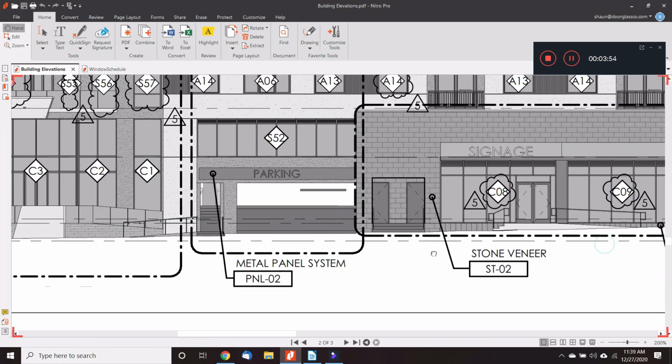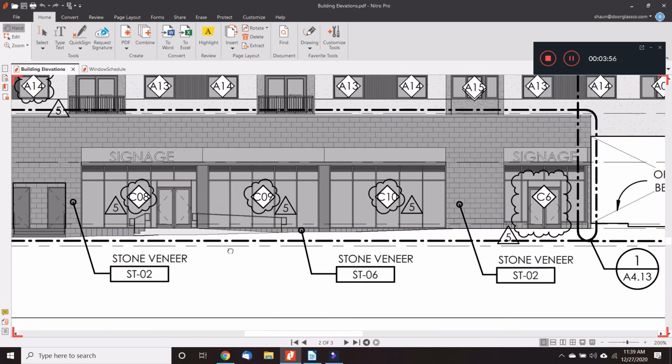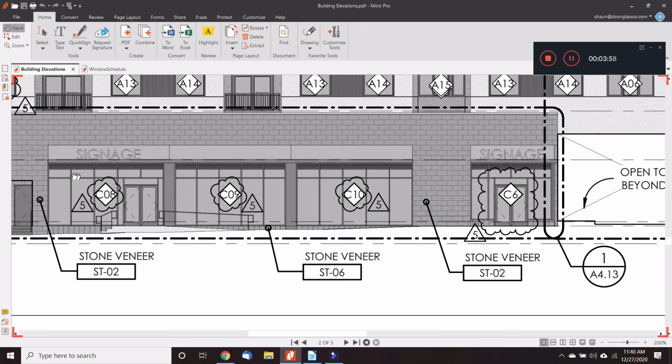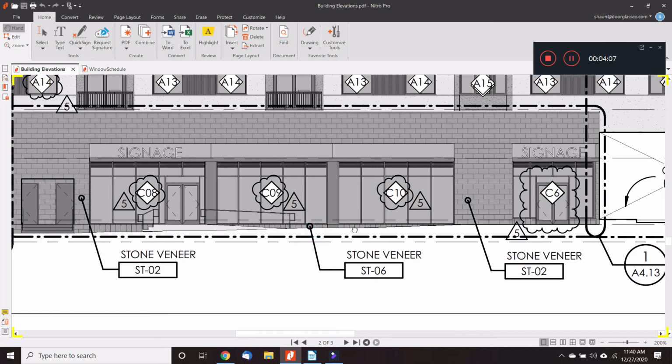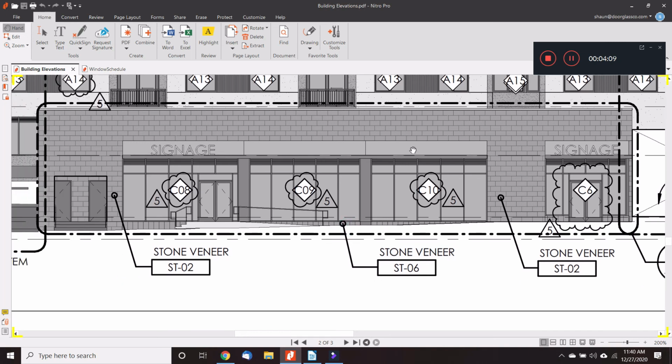Another possibility is that, you can see in our drawing the horizontal elements of these 3 frames line up. Looks like it also is supposed to line up with this. It's possible that when these openings are made, there could be a slope from this side to this side. It could be an inch different in terms of level.